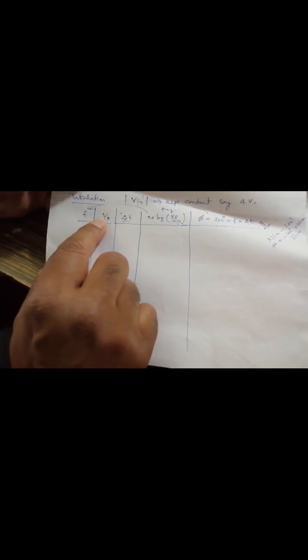Once you measure this, considering the input which is kept constant, take the ratio of V0 and Vin, take the 20 log of that, and you will get your gain in terms of decibels. So one of the plots in our frequency response is magnitude versus frequency. Measuring V0 peak to peak and converting that into a gain with the help of Vin, which is kept constant, you can plot the magnitude versus frequency.